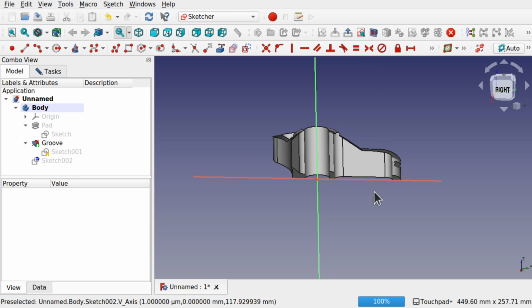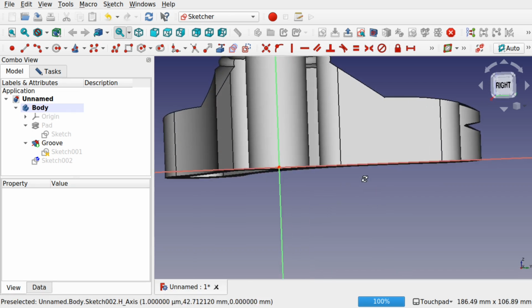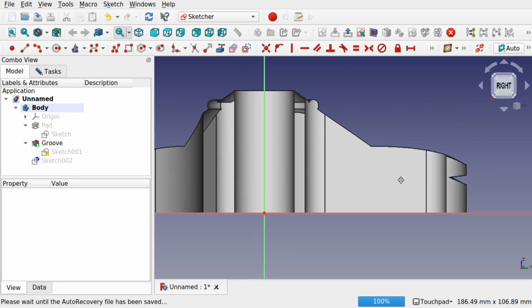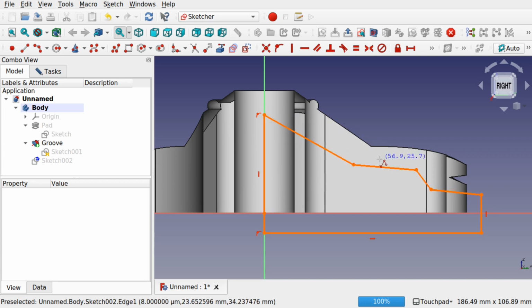Do a section view. And this time I'm going to remove material from the bottom. Click on the right. Let's create a profile through here. So we're going to create a polyline connected to the center and follow this down like so, across, and we'll go down across. So remember, this is going to be removed. Connect and all the way up. There's only one side you want to do it like so.